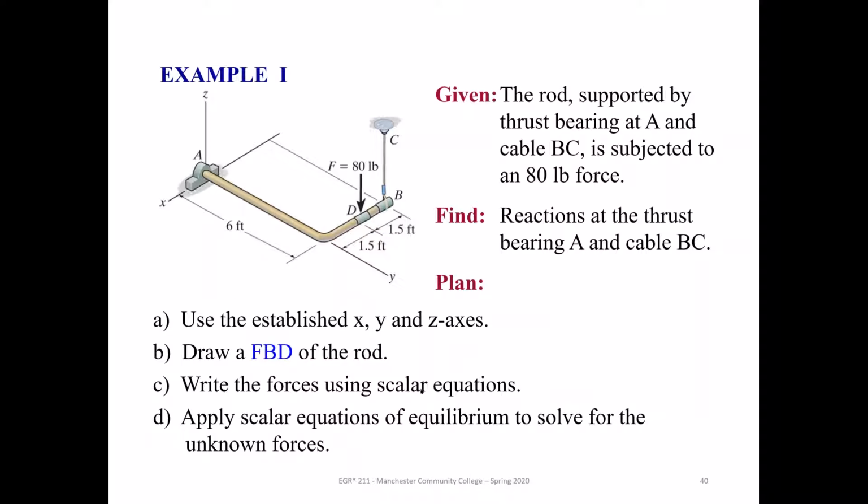Of course, we're going to write the scalar equations for those. We have the moment equations, and you could write the forces as scalars, or you could write them as a vector if you wanted to. But we're going to look at it with just scalar equations. And then you apply these in equilibrium to solve for the unknown forces. This is the author's approach. But in any situation like this, you could put this as a three-dimensional system and then solve it that way.